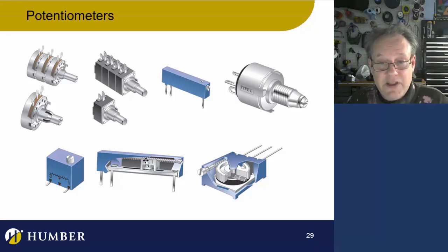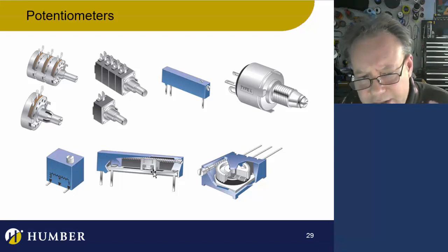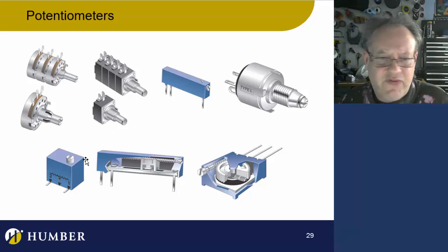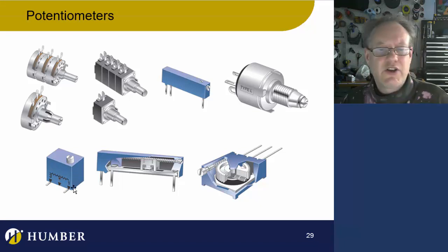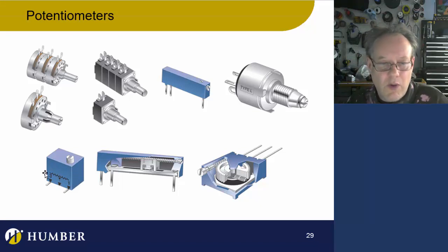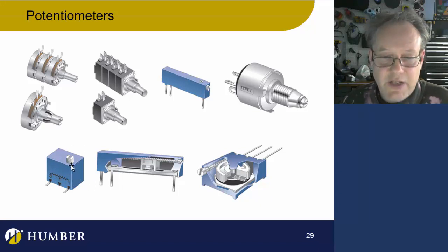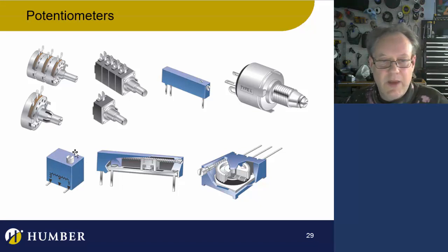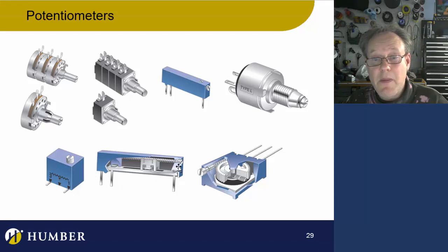And essentially, this is a linear trimming pot. And then some trimming pots are really super crazy sensitive. Like you have to turn it like 15 or 20 times to make the wiper go all the way from one side to the other. And some you just turn, almost all the way, almost 360 degrees. Lots of different kinds. This one, you turn maybe 270 degrees or maybe 365 degrees. This one you turn many, many, many times as this slider goes back and forth.